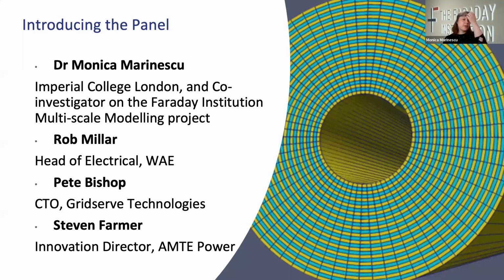And the other direction you mentioned, degradation, I think we are sort of knowing what we're doing now as a community. But we are also understanding how important the coupling between the degradation mechanisms is. So long gone are those days where you would just cycle a cell and attribute its entire degradation to a solid electrolyte interface, just because we know that happens. We now understand that as you use the cell at various stages in its life, different degradation mechanisms play a role, and you need to be aware of those. So coupling of degradation mechanisms within the 3D and thermal models is very much the focus.